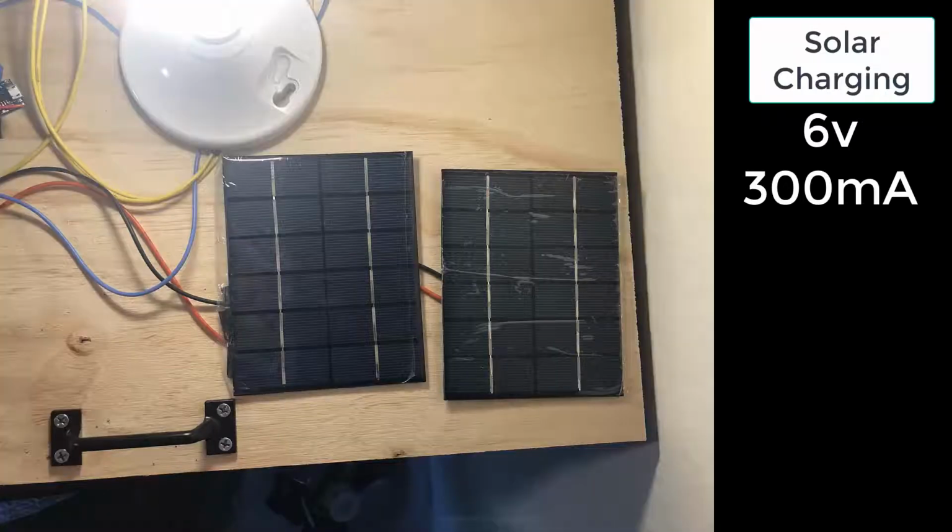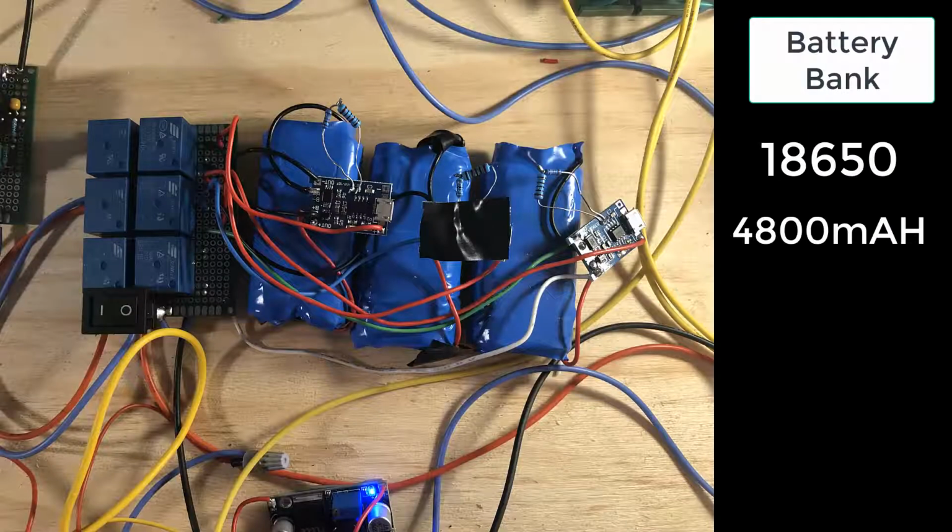Here is the solar array that we purchased. It's rated for 6 volts at 300 milliamps. Putting two of them together in parallel increased our output to 600 milliamps, but for our charging setup we would need a lot more power, which is why we implemented a secondary buck converter. The solar array acts as a slow charger for the battery in the event of a power outage, not a full standalone solution. Next we look at the batteries, which are commonly used 18650 cells.